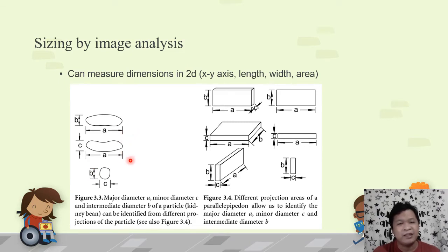Taken at a 90-degree angle from each other, and each one being the shortest length that would encompass the whole projection. Okay, so just imagine if you had a three-dimensional rectangular solid, and you would take the longest dimensions from each side when you rotate it at 90 degrees.